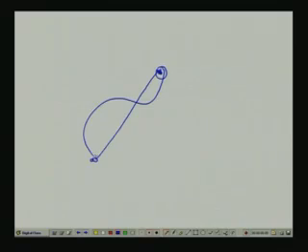But in a contouring system it is very important, because you can see that the contours between these 2 points are completely different. So the contouring system has to continuously maintain velocities along the trajectory, the right Vx and Vy values, so that the desired contour is generated.